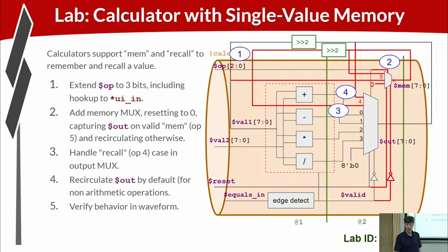this path. Okay. So I'm choosing to loop that around on a 2-cycle loop because the operations are at least 2 cycles apart, right? So when I get a mem operation, the value from the calculation that happened 2 cycles ago is stable, right? I'm not going to change that the next cycle. So this could be a 1-cycle or a 2-cycle loop. It'll be stable in that window.